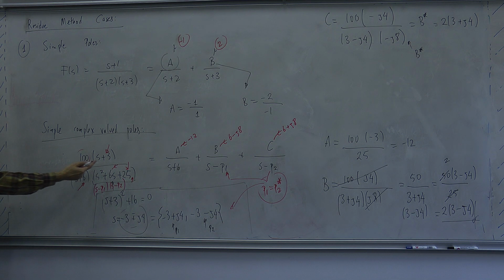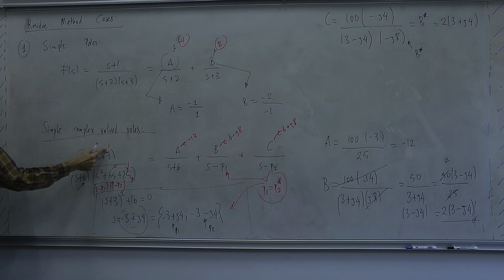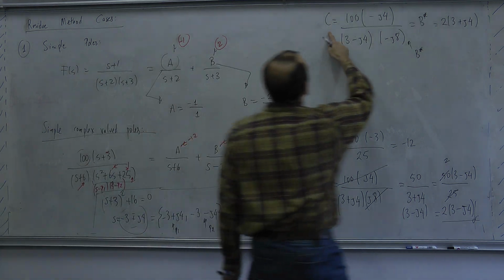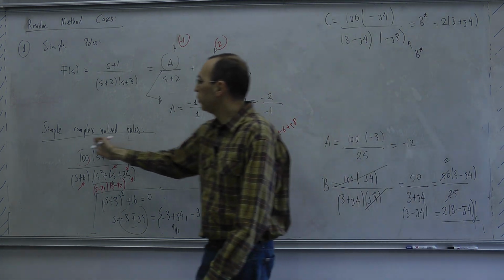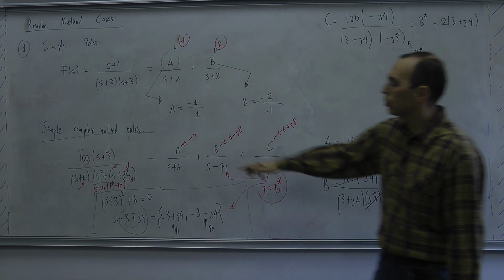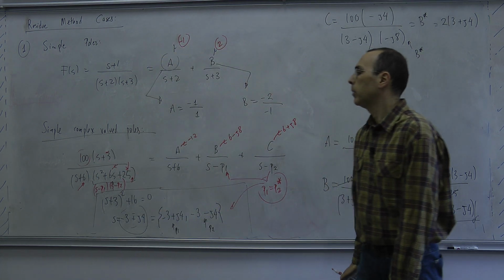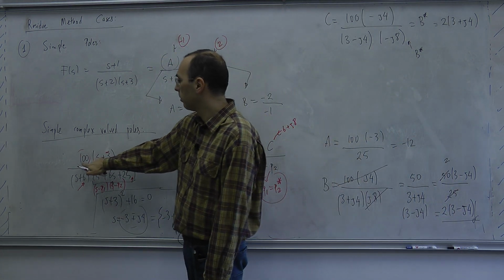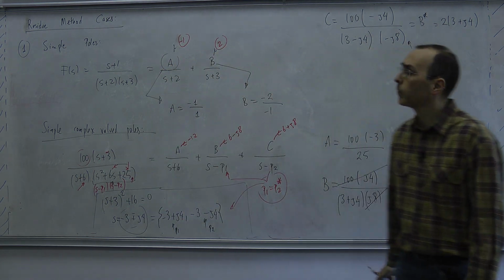So if this coefficient is complex valued, clearly, if you take the conjugate of this result, if this is like J3, it will be minus J3, and we don't have this kind of equality, okay? Because at the end, if you calculate the B and take the complex conjugate, you're also changing your f of s function at the beginning. But luckily, our f of s function is a function of s, but the coefficients are real valued, okay? That is the deal.